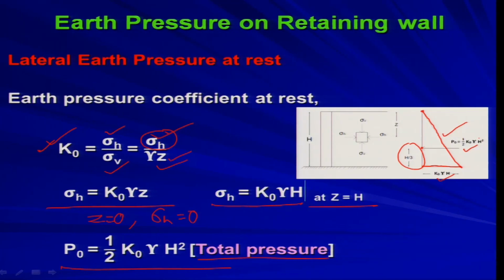So, based on that you can design the wall. The wall should be designed based on the total pressure acting at that level. That is earth pressure at rest condition.